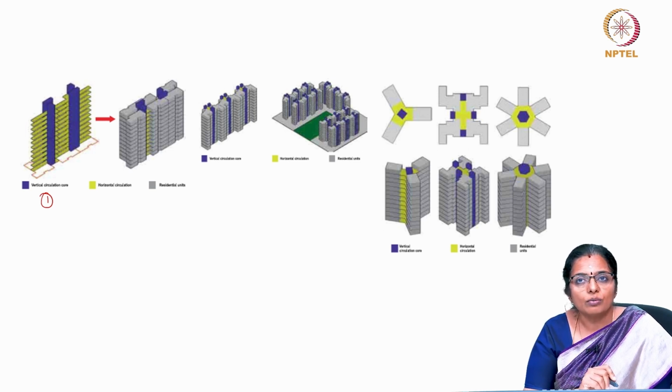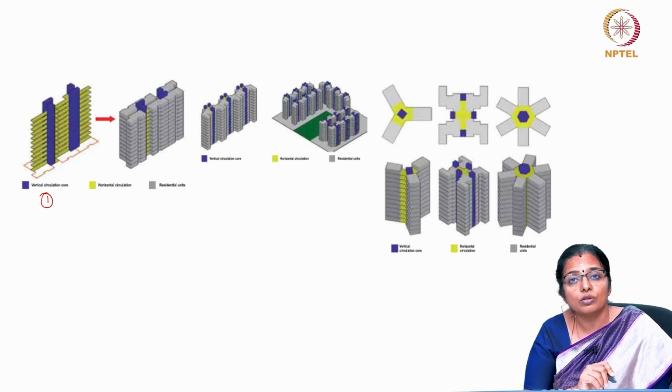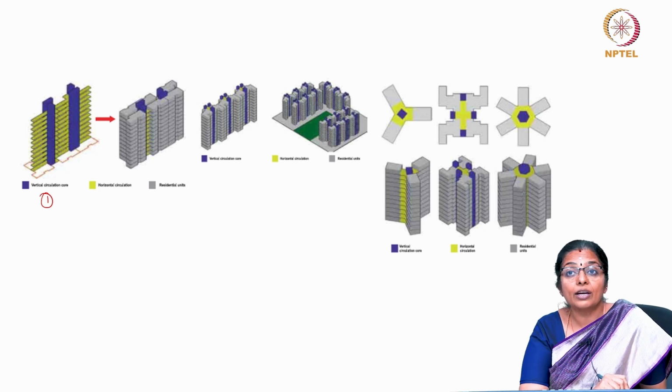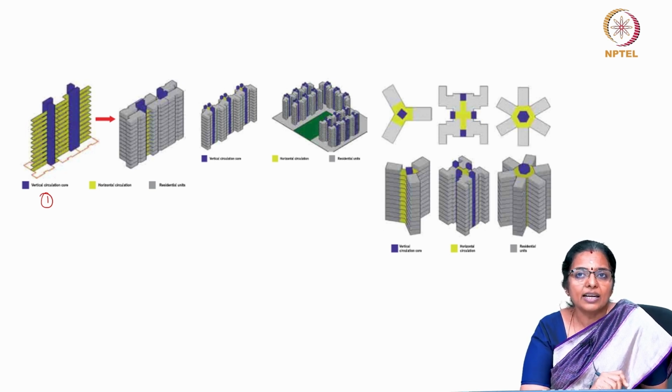Regarding the volume, the patio house is the most suitable form and can benefit in summer from the microclimatic effects of cool air pools that occur in courtyards. Although winter conditions in hot arid regions would permit an elongated house design, the heat in summer is so severe that a compromise is required.